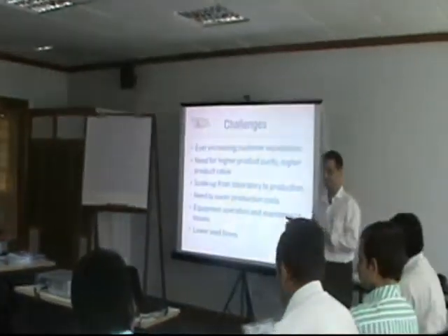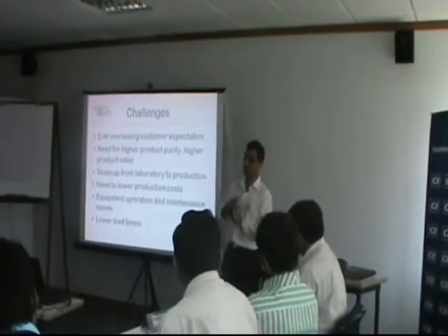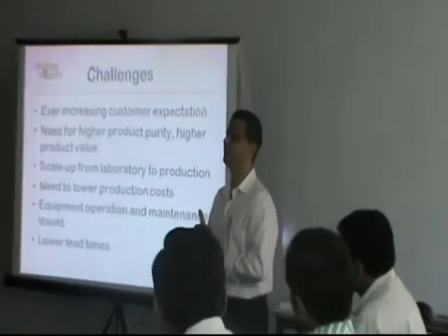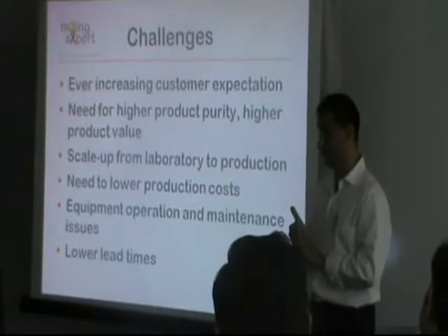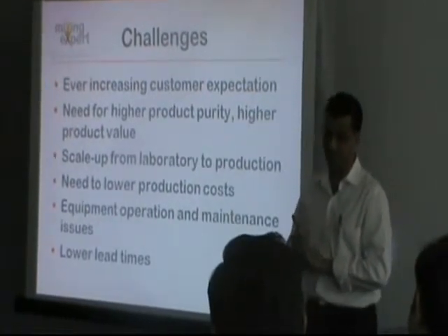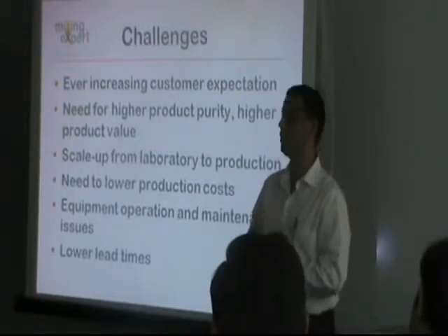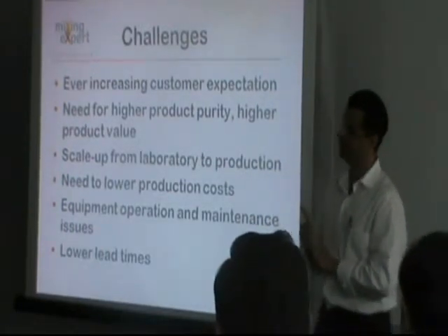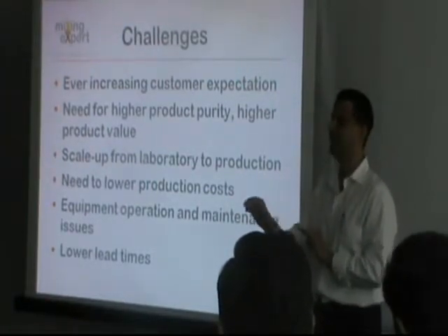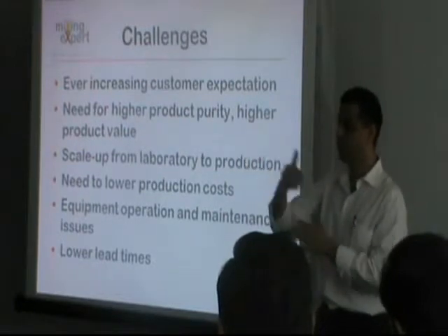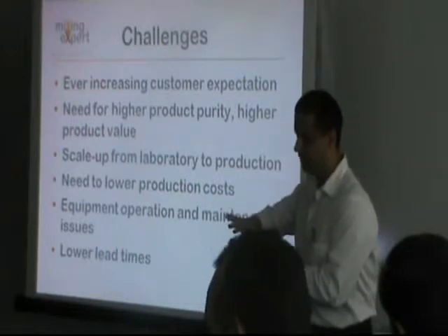As a thumb rule, considering that we are operating at 415 volts and 50 hertz, you could take that the maximum rated current for a motor is 1.5 times its horsepower. So current in amperes is 1.5 times horsepower. It keeps varying, it could be 1.3, 1.4, 1.5. But as a thumb rule, it is a good measure. So if you know the amperage, you can back calculate the kilowatt using this guideline.